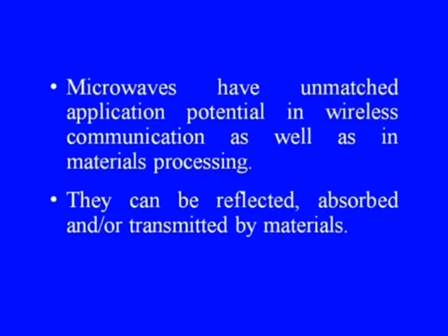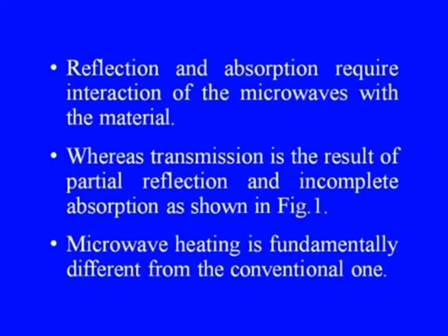Microwaves have unmatched application potential in wireless communication as well as in materials processing. They can be reflected, absorbed and transmitted by materials. This I have already discussed. Reflection and absorption require interaction of microwaves with the material, whereas transmission is the result of partial reflection and incomplete absorption. This we will see in terms of another figure.